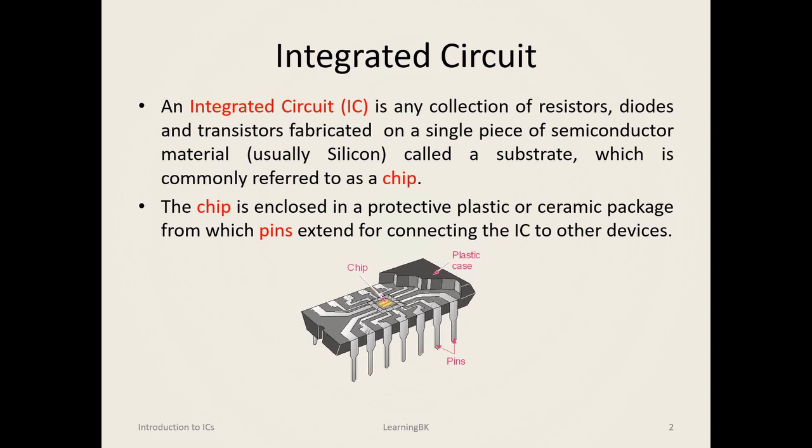These pins, which we physically see coming out of the package, are basically used to connect this device to other devices or to a printed circuit board. In our case, these pins allow us to mount these chips on a test board, on a Vero board, or on a breadboard, and then we can supply power, apply the inputs, and observe the outputs.